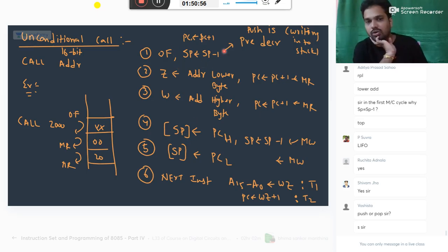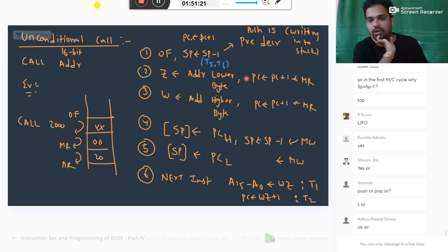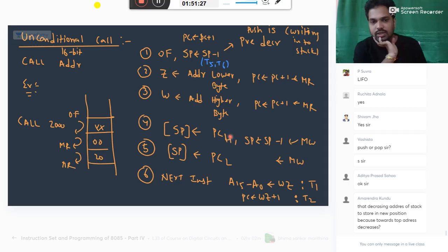You should do it during the opcode fetch only, because these memory read and memory write are fixed 3 machine cycles. In that, PC is already doing it. It is fixed. So here the computer designer has made it like this. Because of this operation, you require an extra 2 T states. Is it clear, Aditya? Okay, fine. So during this period, your PC is not involved. The address bus is copied with your program counter, all those stories same. So now listen here. How much time is required? Let us do it now.